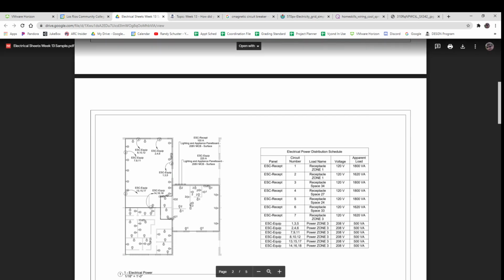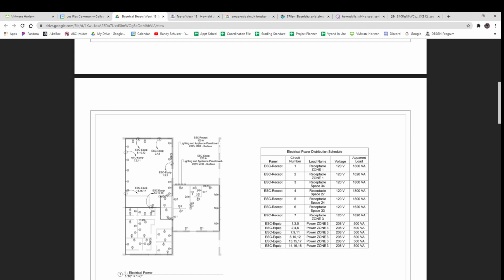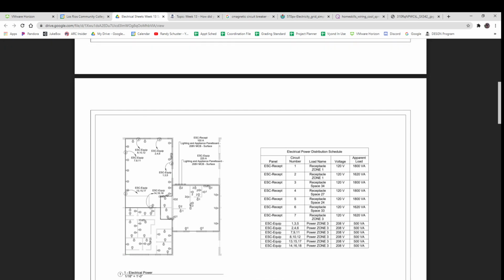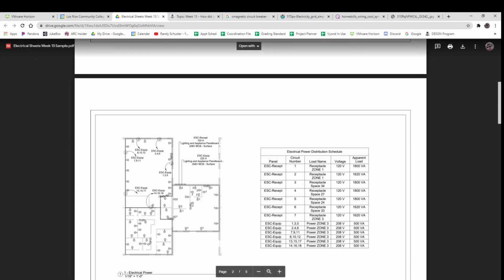You'll see that there's 2 things. There's receptacles and junction boxes. Receptacles are already wired up and there's a plug that you plug into it, that you put your device in. It's the wall receptacles that you've got. And then there's things called junction boxes. It's basically just a box where the wires are there and they've got caps on the ends of the wires. And if I have a lathe or a mill or something, an electrician does the work to wire my piece of equipment into the junction box. So that's called a junction box with a load. And so I can set those up.